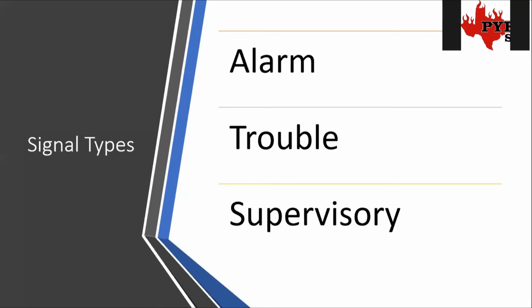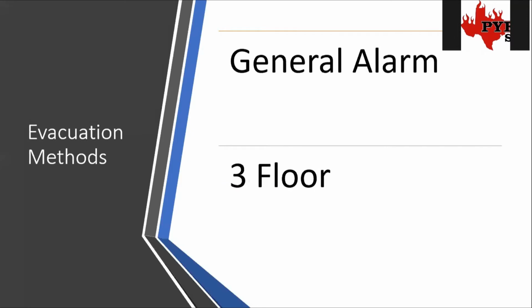And then something else we're going to need to talk about is there's two types of evacuation methods. The most common one we see is general alarm. This is for every single building except high rises. So whether it's a school or a little lease space, warehouses, whatever, when the entire building evacuates at once, that's general alarm. Low rises and mid rises are also general alarm.